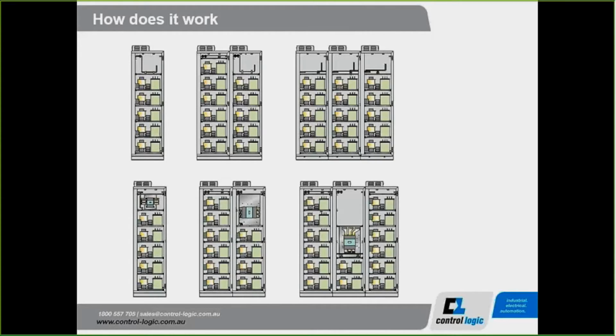So the power factor correction unit then knows, this is my current power factor, this is my load, this is my target power factor. It then calculates which of these trays or steps it needs to pull in. It could just simply pull in one tray, or it may need sufficient more capacity, it has to pull in multiple trays. And these trays don't necessarily all have to be the same power rating. You can have 12.5 kVAR, 25 or 50 kVAR steps in the ABB range. So the power factor controller will work out how many trays to pull in.